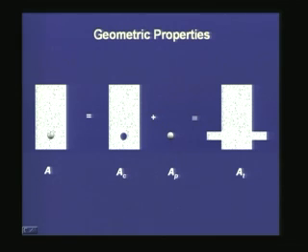This prestressed section is equivalent to a transformed section where the full section is considered to be of concrete. That means the prestressing steel has been substituted by an equivalent area of concrete. Now, this transformed area is considered to be made up of only one material, and that is used in the elastic analysis, which is similar to an elastic analysis of a homogeneous material section.